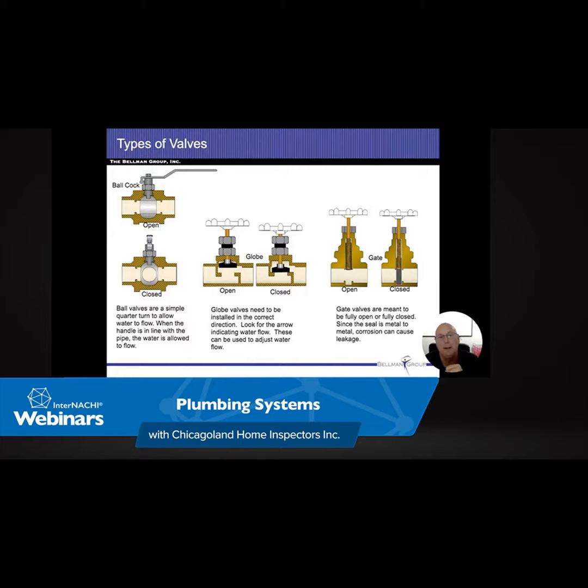If you don't drain it periodically, then there's a chance for hot water to get trapped at the bottom under the debris. Absolutely. You're talking about the gurglers, aren't you? When that pocket escapes, it could trigger a too-hot warning that will shut the water heater off. That is a great add.